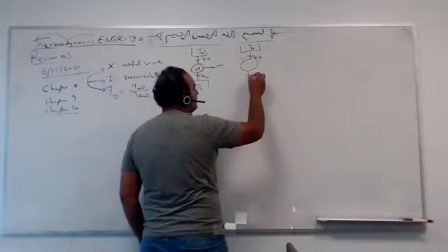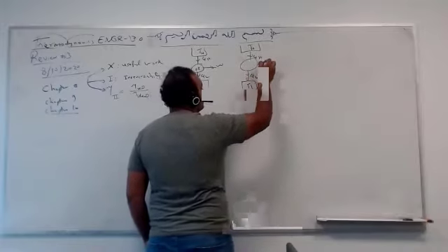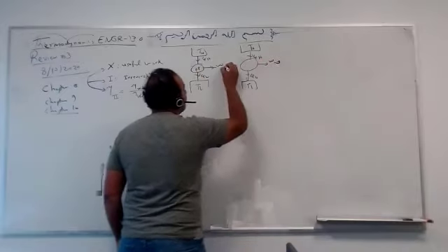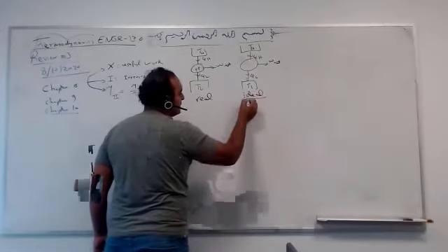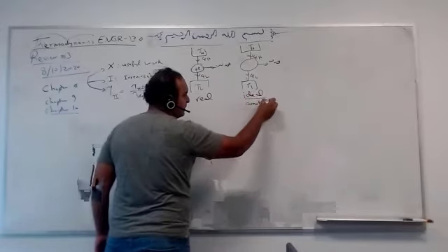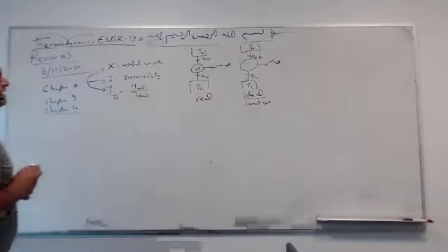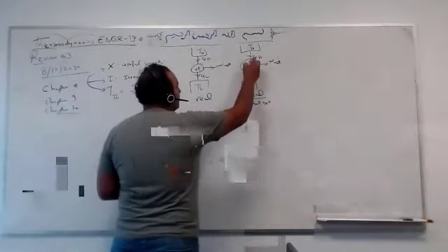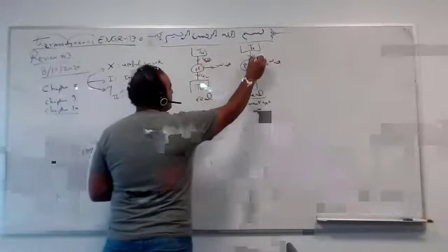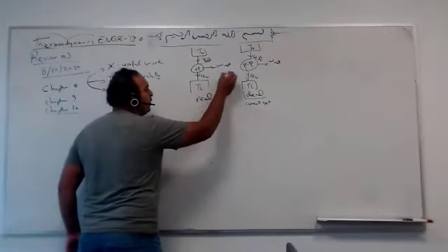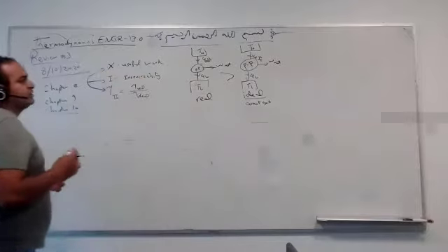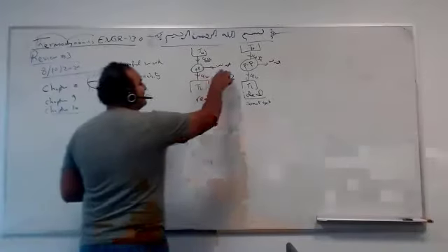Oops. Q low. We have here, this can be real or ideal, like Carnot cycle, the most ideal or most efficient cycle. See, this power plant, we have the same heat. This one is the same as this one. So what happened here? In reality, we have more losses. We have more Q low. Q low is larger. We have more loss, or the W net is less. So in reality, we get less work.